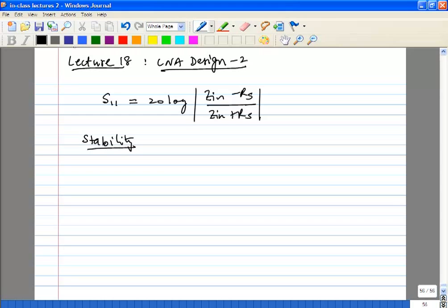And remember, your input and output matches, in case you have an LNA where you need to do both matchings, there will be some dependence. There will always be some dependence because you have GM the forward way, CGD for the reverse way. So you'll always have some dependence.